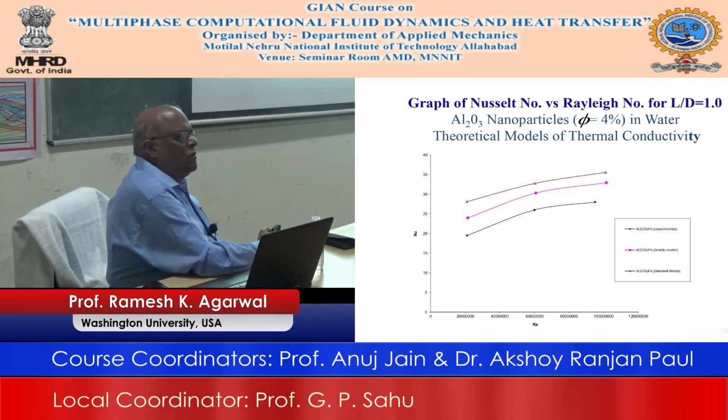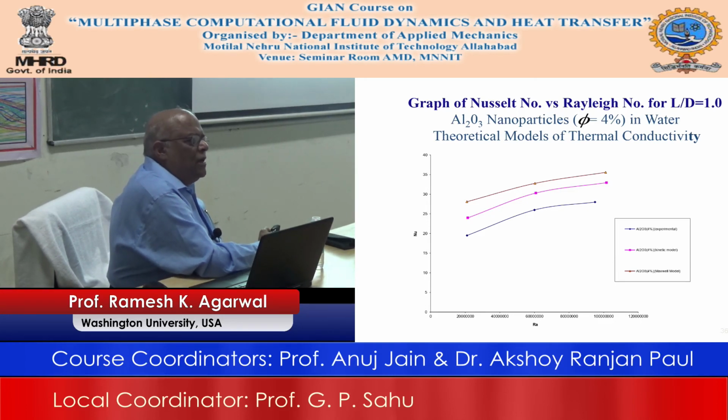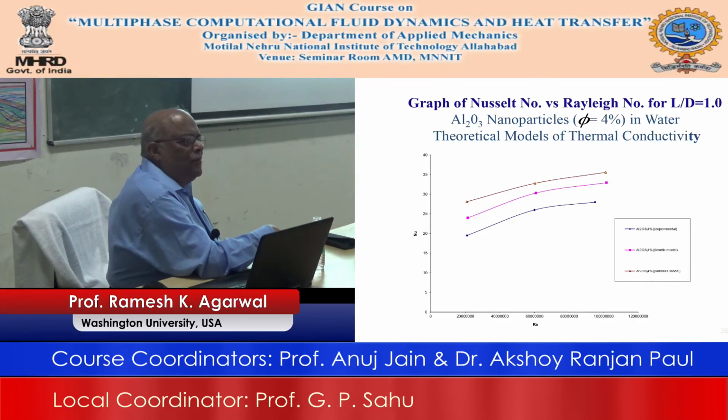And now, as I said, there are tons of models there. We are not working on this project, so somebody who wants to do it can try it in Fluent as it is, by simply changing all these values of rho, mu, Cp, K, beta, and then you can get some results.